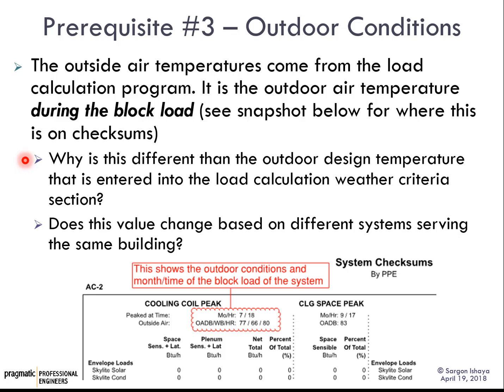So when it's very, very hot outside, let's say at 2 p.m. or 1 p.m., the heat from that peak temperature of the day will not penetrate the concrete until several hours later. And that's why often we have a peak, you can see here, at 6 o'clock. It's late in the day, but that's because the building has a thermal mass. So when it was much hotter at, let's say, 2 p.m. in this building, 1400 hours, the heat didn't immediately enter into the building.